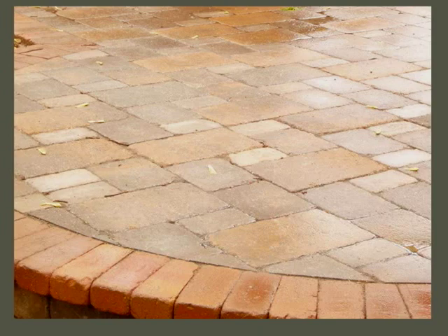So remember that road base slide we saw a little while ago? So the road base is super awesome because you're not pouring concrete. It's not that complicated. It's permeable. And that's hugely important because water can soak down into the ground. We're not creating as much runoff. And it also, probably the greatest limiting factor in everything we do outside in Colorado is freeze-thaw cycle, right?